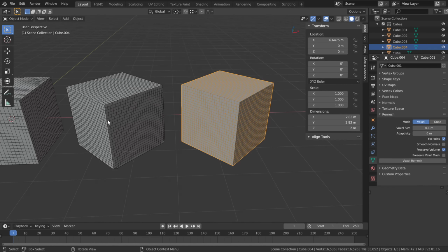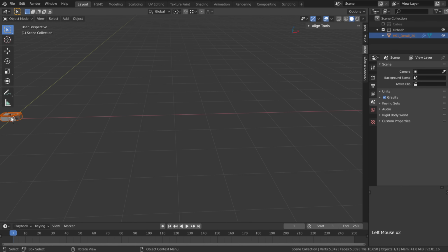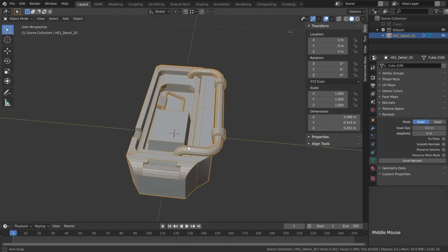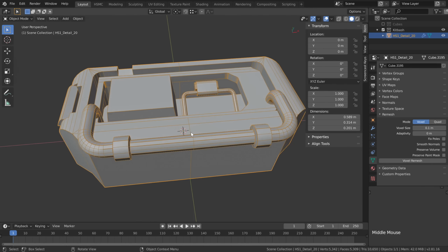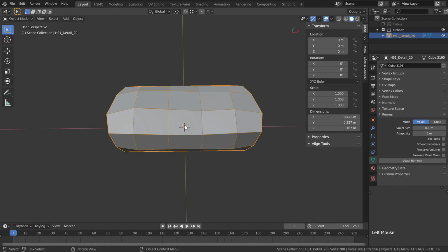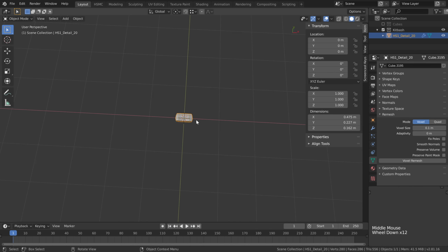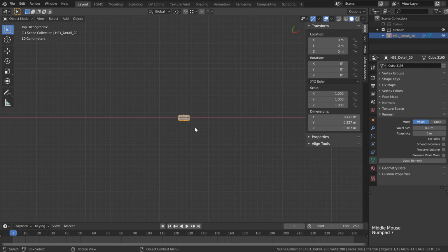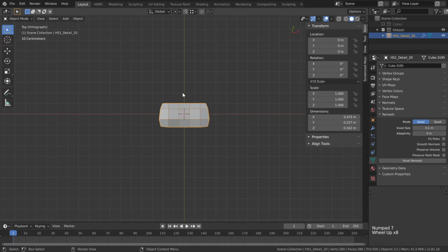So something we've hinted at there with the object rotation would be similar to the object scale. So I'm going to switch off these cubes and just take a look at this kit bash item from the hard surface modeling course. This is a very basic, very simple object, and we can see it's got a scale value of 1 at the moment. And if we voxel remesh, we can see it's not doing a very good job because it's actually quite small. So again, if we take a look from top orthographic view, we can see our grid spacing. So we really didn't have enough resolution for that.